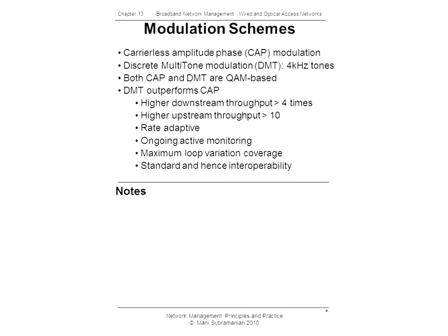So when we discuss different types of customers, we can see that not all residential customers could have the privilege of getting ADSL service. Only those who have direct copper connection from the central office could be served with ADSL. So telephone loop facilities with loaded coils do not qualify for the service.